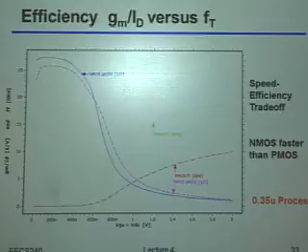As we've been hinting at throughout this lecture, what we can always do is look at how we trade off between our current efficiency, or our gm over ID, which means tweaking our V star, versus that omega t, right? I apologize, the colors here are not great, so let me try and fill in on top of this curve.